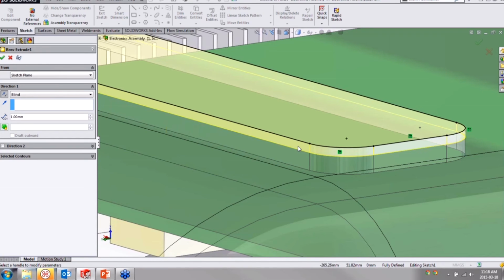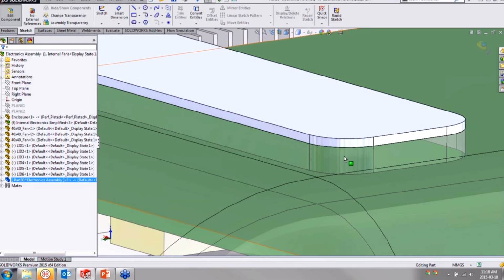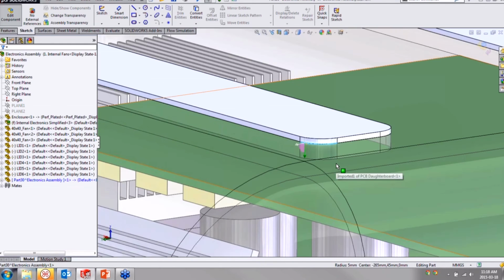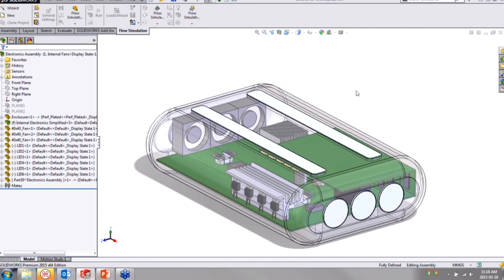The other way that people end up with a zero thickness condition, and this is really common, is actually just extrude the wrong direction by accident. And so if I do that, I'm going to end up with zero thickness along these edges here. Now, let's say you go through, you create these lids, and you mess up. You don't spot these problems. How do you find out about that?